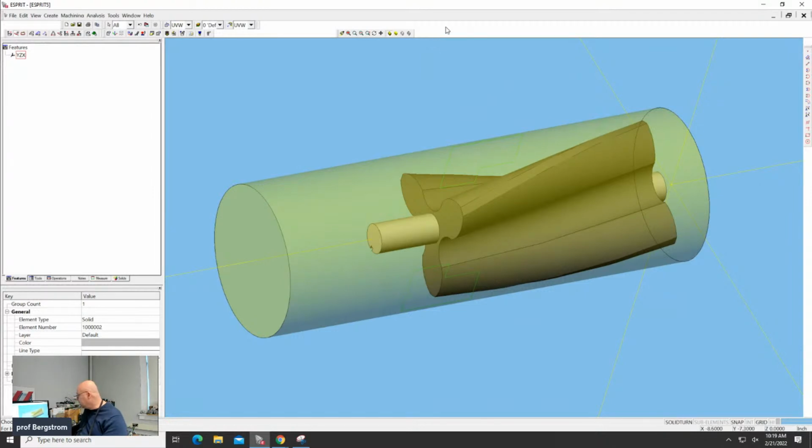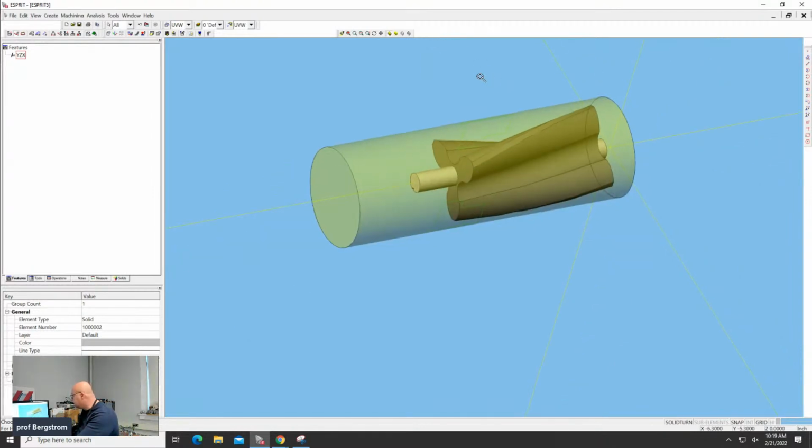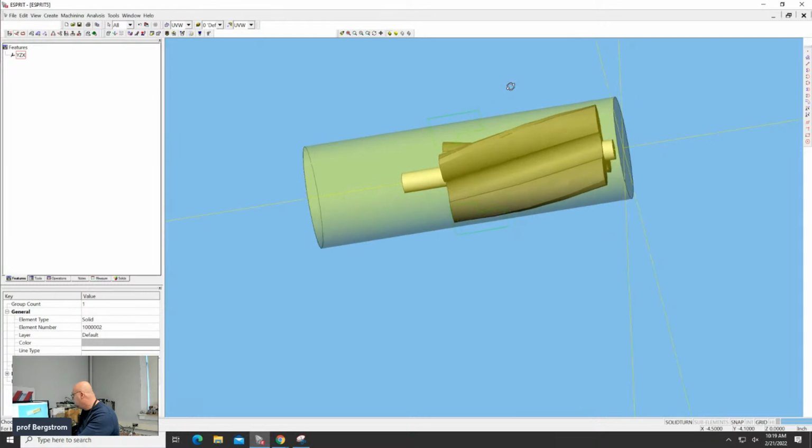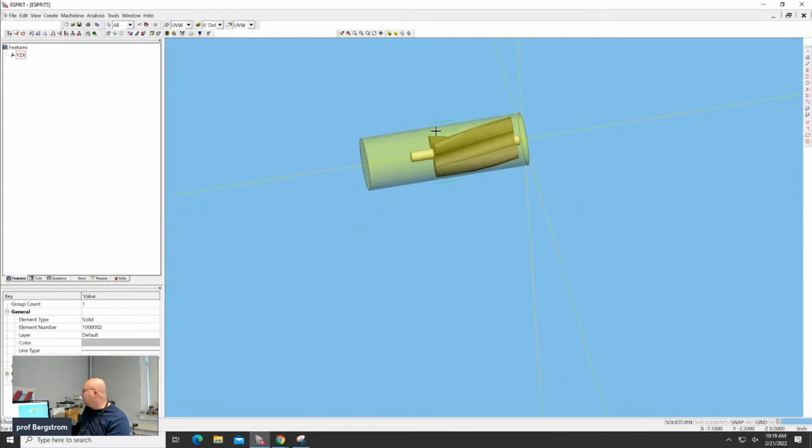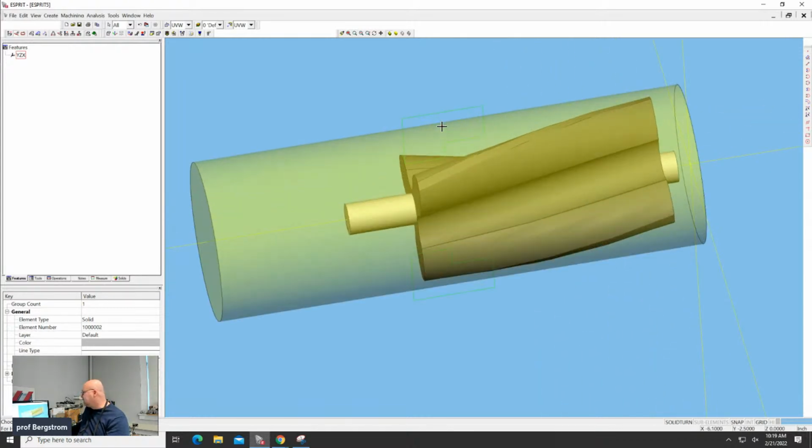All right, so I think what I would do first in this situation, well, so we're holding it. The chuck is over here. We want to have plenty to hold on to when we do our other operations. I would do a turning operation first to get it close to the right part profile. What's up? Are the green shapes, are those not representing the chucks? What are those representing? Oh yeah, that represents the chuck in the simulation.